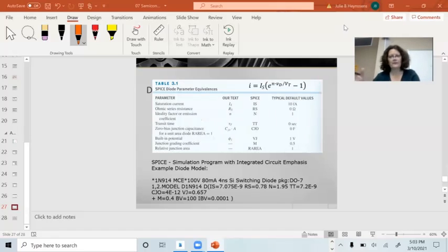The way you get around this, and I was doing this over the summer, I was modeling a device that looked like a capacitor, but we were able to inject small DC currents through it. The only way I could model that as a linear model is I took a capacitor and put a really big resistor in parallel with it. And then I could get my 100 nanoamps through there and have a semi-ideal model,